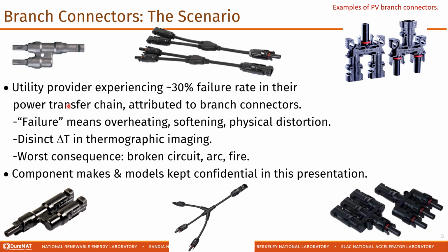So we were approached by a utility provider, and something like a third of their strings were dropping out, and this was attributed to the branch connectors. Failure here means overheating and softening of components with physical distortion afterwards. There was an overt rise in temperature for certain components in FLIR imaging, with the worst consequences being broken circuits, arcs, and fires. So I show some examples of branch connectors for the PV industry here, but the actual make and model that we're studying is going to be confidential, at least relative to this presentation.